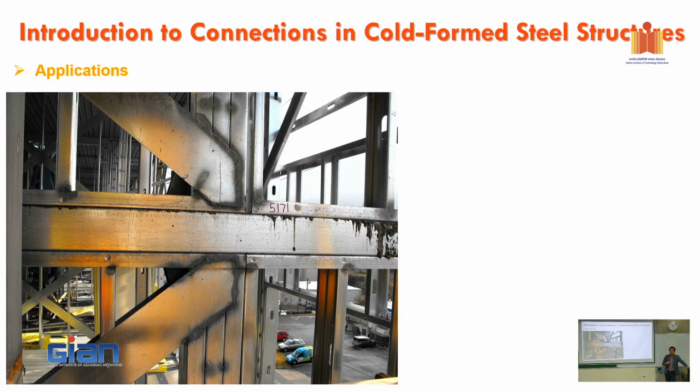You just assume that the connection is subjected to every single action, or subject to different failure modes. For example, you check the screw for shear, you check for bearing, you check for tilting, everything, and then at the end you choose the smallest one, which will govern your design.